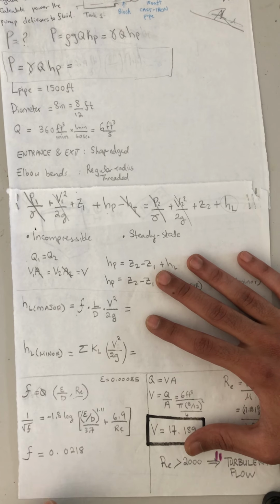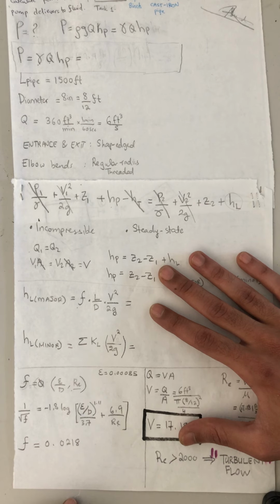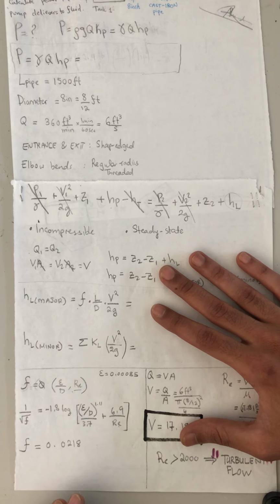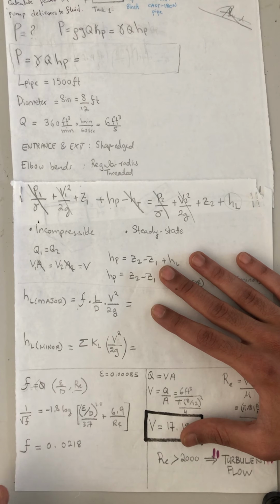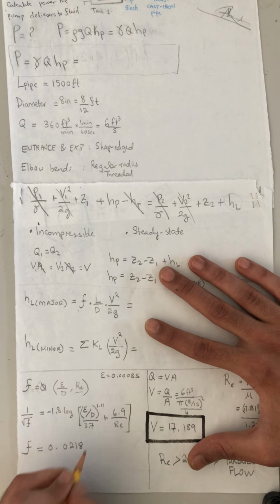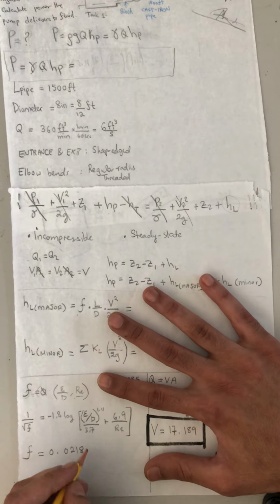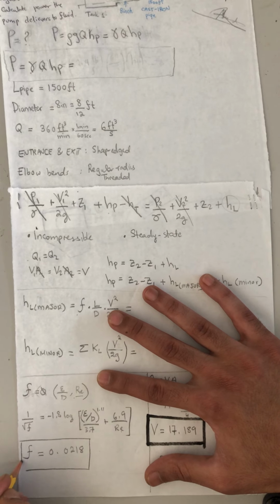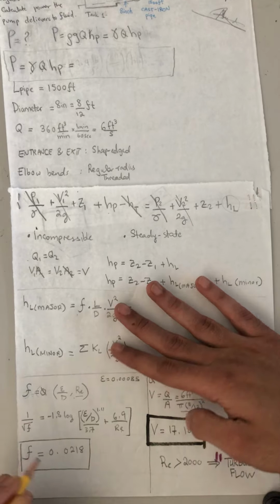To double check my frictional factor, I have used a website that can determine the frictional factor by providing the website my Reynolds number and my relative roughness number. This value is also a very important value in our solution.